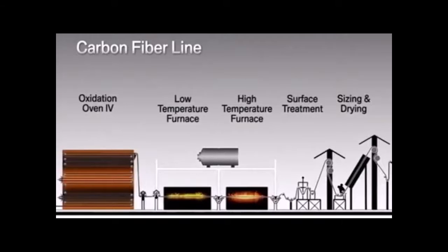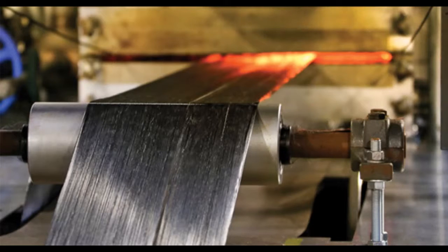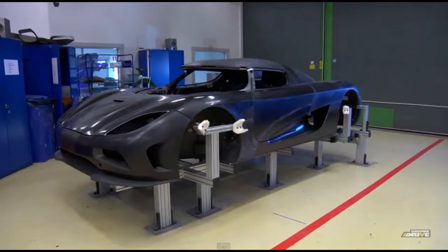Carbon fiber is produced through both chemical and mechanical processes. First, polymer strands are brought together into fibers, which are then heated in the absence of oxygen. This process, called carbonizing, expels most non-carbon elements from the fiber and leaves a tightly packed chain of carbon atoms.